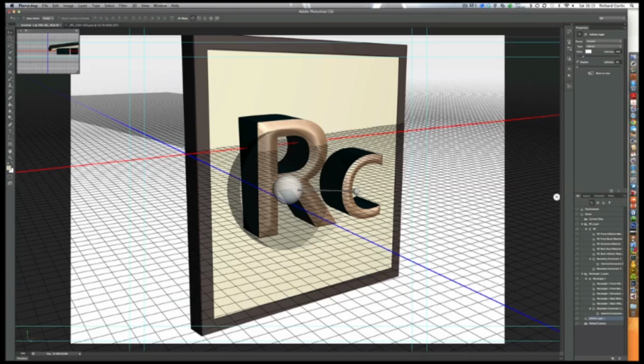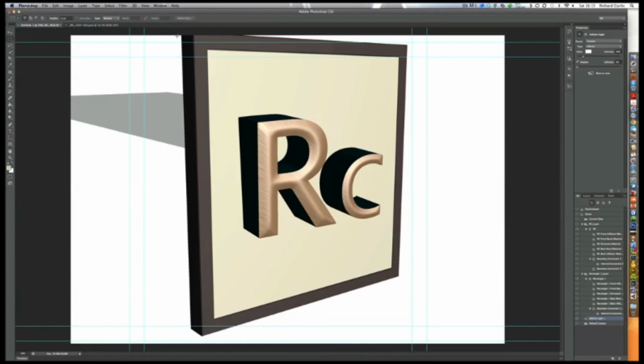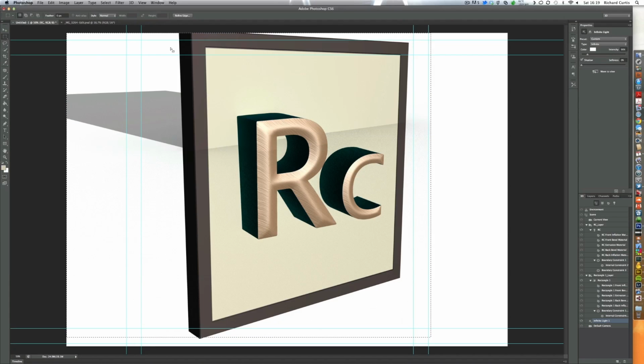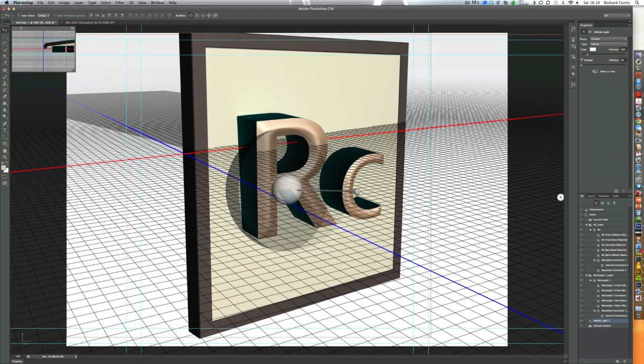Okay, so if I just render this quickly, I want to see just a quick final preview of what it looks like. I'm going to highlight the whole area with the marquee tool, and then on the properties panel I just choose the render option, making sure that my 3D scene is selected. Now the render is complete, you can see we have a slight issue. We have this dark line going through the scene here. The plane goes straight through the object we're building. We need to be above the plane, so we need to move this scene out of the way slightly.